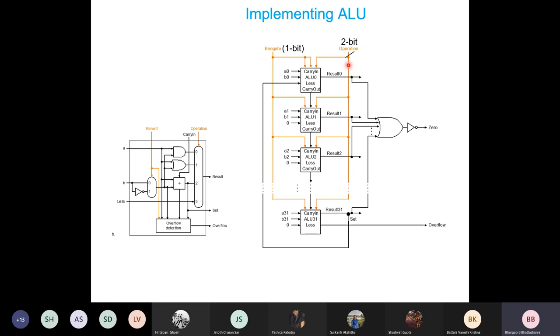And then to implement a 32-bit ALU, what you do is very simple. You interconnect them in series. And as far as the adder and subtractor are concerned, we are emulating a ripple carry implementation. All right, as simple as that. So you see that you have A0, B0 running to A31, B31, meaning that this can now process two words, two operands, and you may implement logical AND, or addition, subtract, and so on.